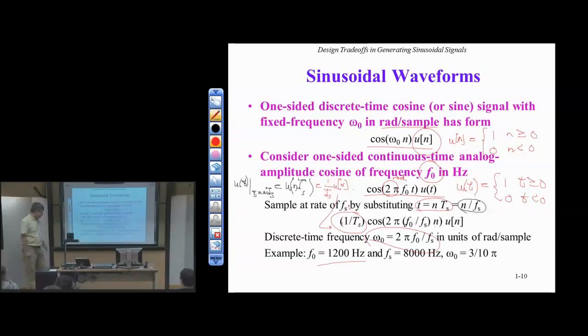So is that actually how they generate it, like a full string without having to code more data into memory? Yeah, so if you really want to generate a pulse train, you really just have to generate 1 and -1. You don't have to go through all of this computation to get a cosine and then typecast. There are faster ways to do this, which is you let it be 1 for a certain number of samples and then -1 for a certain number of samples and repeat that. It's a very fast algorithm. This would be a very slow way to generate that. So yeah, we would do it a different way than this.